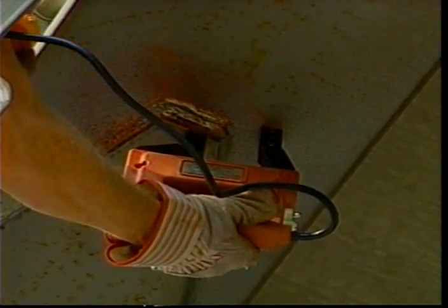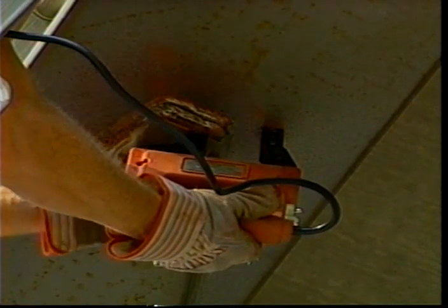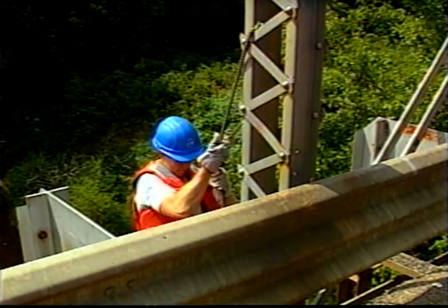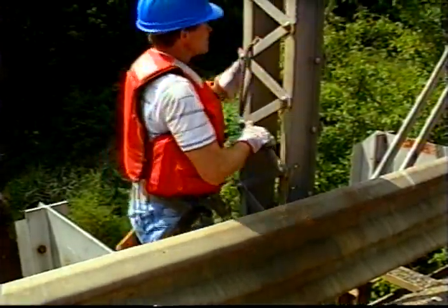Iron compounds are applied on the member and are attracted into recognizable patterns in the area of a flaw. The dye penetrant method is used to detect cracks by applying an oil-based liquid dye, which is absorbed by the crack. After removing excess from the surface, a white liquid developer is applied, and dye extracted from the crack becomes visible. Radiographic inspection uses X-rays to locate surface and subsurface defects in steel members. Other inspection techniques and applications can also be applied as appropriate in the variety of situations, materials, and members encountered.